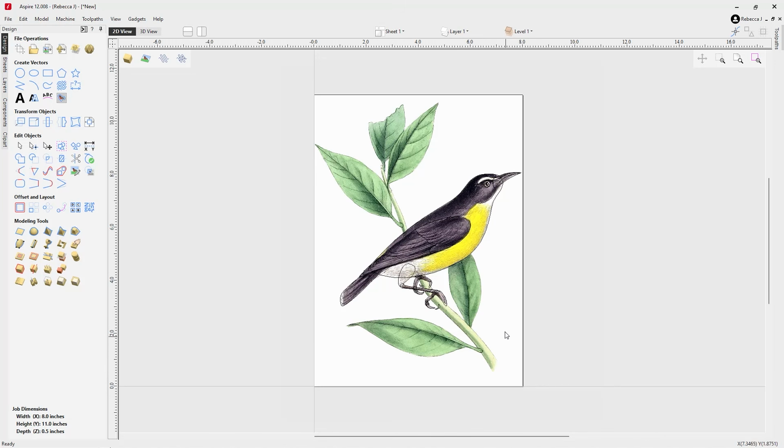And I'm going to draw in my own rounded cross section. We're going to look at how we can sweep that cross section between the 2 rails. Same applies for the leaves as well. So I'm going to have a vector that represents one side of the leaf, a vector that represents the other side of the leaf, and then I'm going to look at creating a cross section that looks as though we are looking through the leaf, and you'll see how we kind of create a shape for that. That's going to give us a really nice leaf effect. It always works well in the leafy natural projects that I've done before.